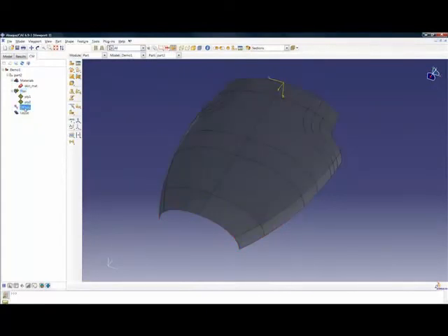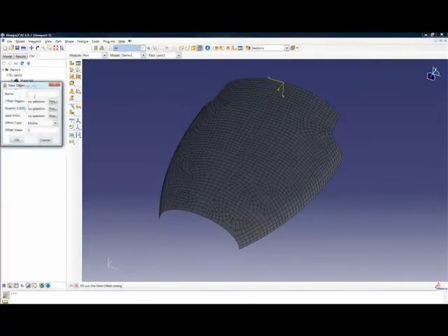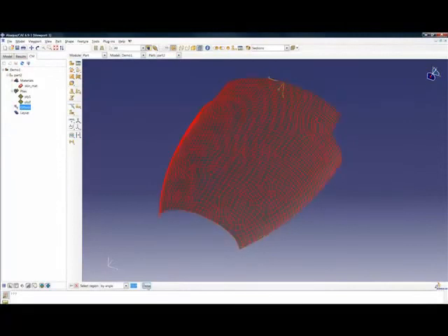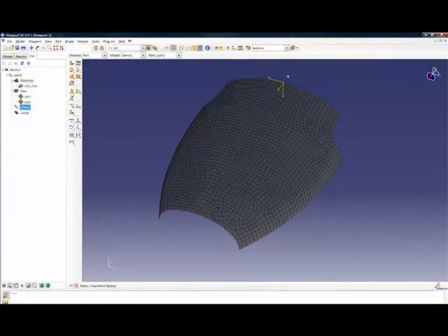The next object is the offsets, which, as I mentioned, is basically saying whether or not the plies are built on one side of those surfaces or whether it's a mid-plane. Give an appropriate name again. Pick the region for which this offset will apply. We've actually selected the whole of the surfaces again.